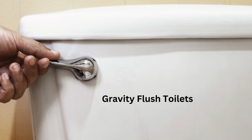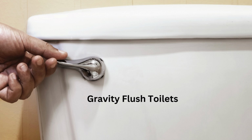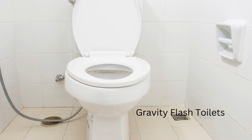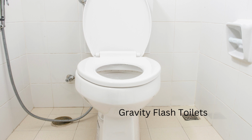The basic design of a gravity flush toilet includes a water tank located on the back of the toilet that holds a certain amount of water. When the user flushes the toilet, the water from the tank is released through a siphon tube, which creates a vacuum that pulls the waste and water from the bowl down through the trapway and into the plumbing system.